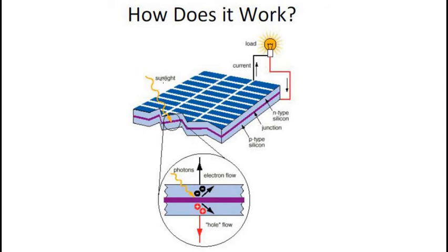So sunlight will enter the PN junction by the P layer, and the light entering it will create a number of free electron and hole pairs, and the thermal equilibrium of this depletion layer will break, and free electrons in the depletion region can quickly come to the N layer.